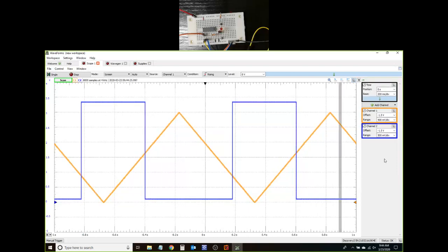So that's how you would do this experiment with 7414. You've got two thresholds here. Clearly, how do you know whether they are true thresholds or not? As you can see over here, the output switches high at a different input level compared to going low.